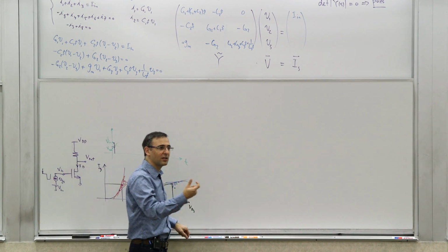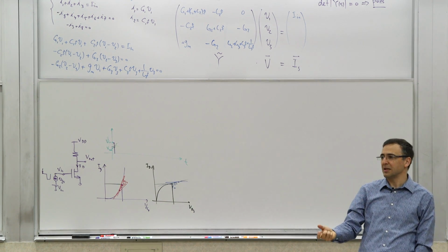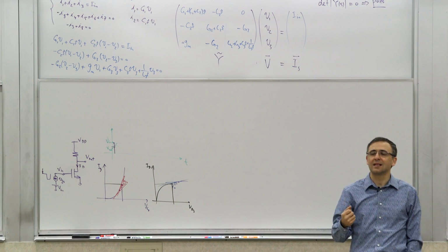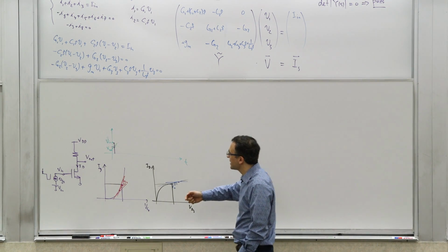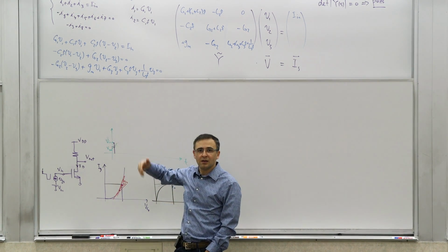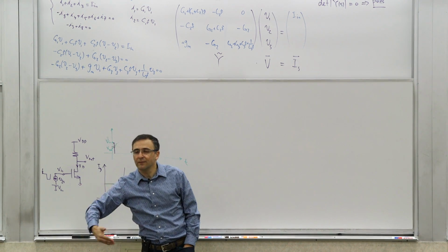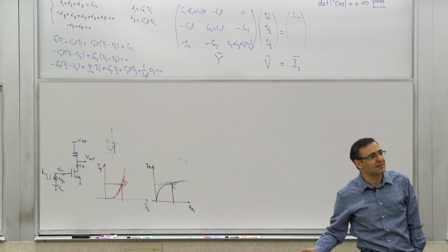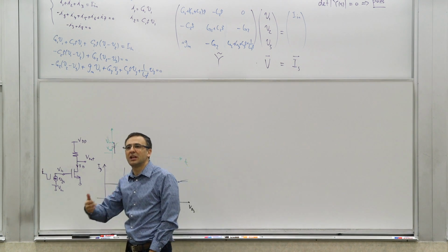Now, how do we decide on the size of the step? We say, OK, the change in each step should not exceed a certain maximum, and that sets the tolerance, one of the tolerances. So you take this stepwise iterative process, and you constantly solve the nodal analysis. You do a nodal analysis repeatedly on this modified, updated operation point that's coming from the nodal analysis that you've already done. So that's how the simulator actually works.